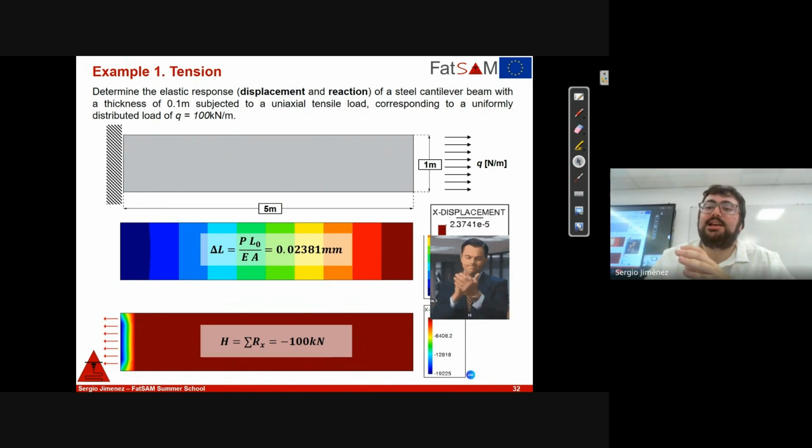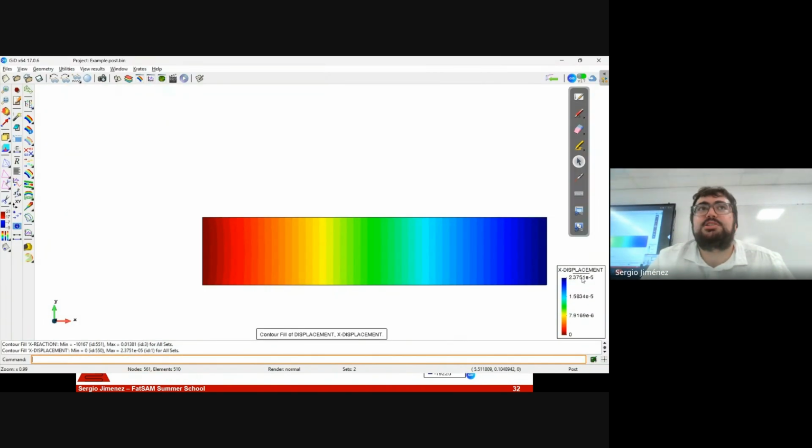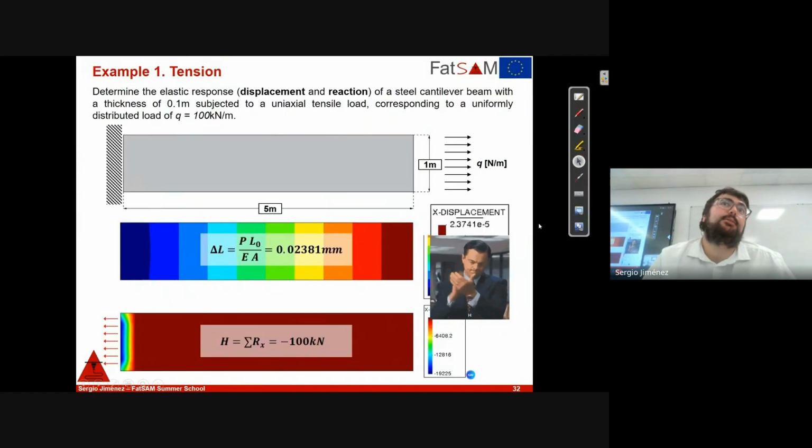But if you are just getting this value or the one that I get, the first question is, which one is the good one? The one which is closest to the converged result. So the first thing that you should be doing in this sort of analysis is ensuring that the mesh you're proposing is good enough in terms of some convergence, some sensitivity test, okay?